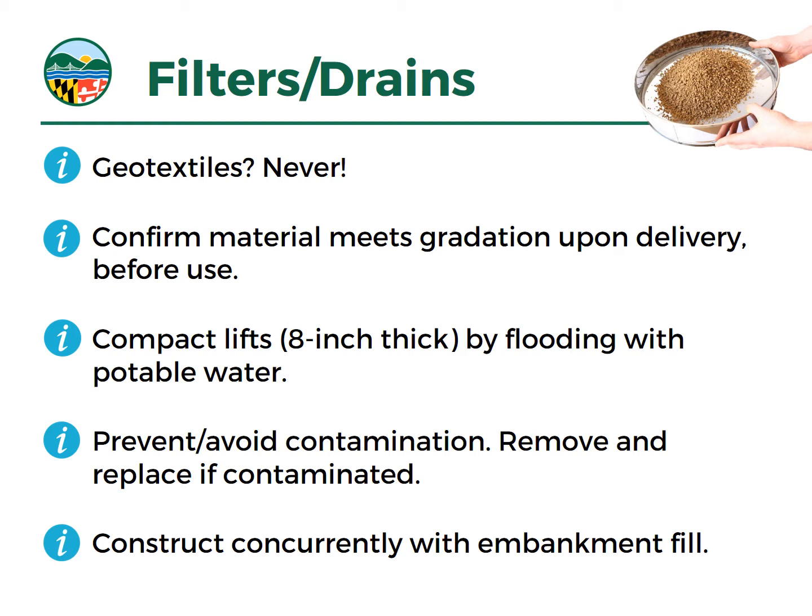Your filter design should be performed beforehand, and it should be part of the project review. But we want to make sure that when you get a manufactured aggregate delivered on the site, you confirm with a new sample and a new grain size test that the material meets the gradation you're expecting.